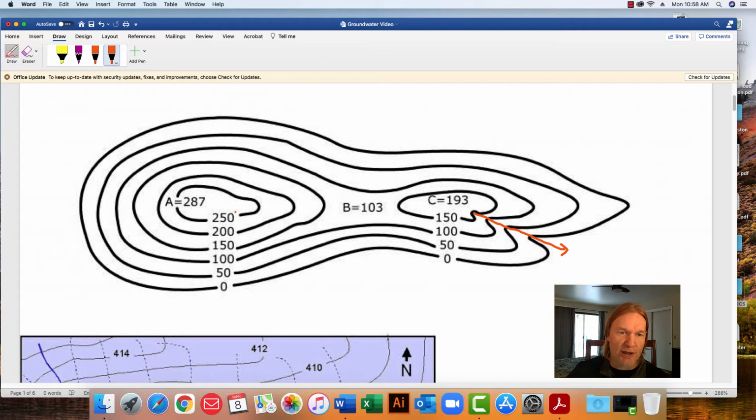So back to our contour lines. Again, I put a little dot right here last time, and I drew a flow line that was perpendicular to these contour lines, and it went something like this. Now I don't really have a protractor or anything, but I know that this is approximately how water would flow over this surface. How would it flow over here? Well, I'm going to use the same principles, and I'm going to just draw the flow line perpendicular to the contour lines, which are black, and it's going to go just about like that.